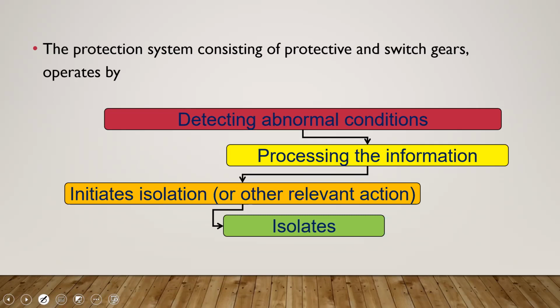Well, what you would consider instantly, all right, think of it this way. Your breaker is rated at 15. Most of our house sub-circuits are 15 or 20 amps, yeah? Yes, sir. All right. Now, if you were to run any sub-circuit in your home at full load or near full load, and go and touch the wire on that sub-circuit, you're going to feel it being quite warm.